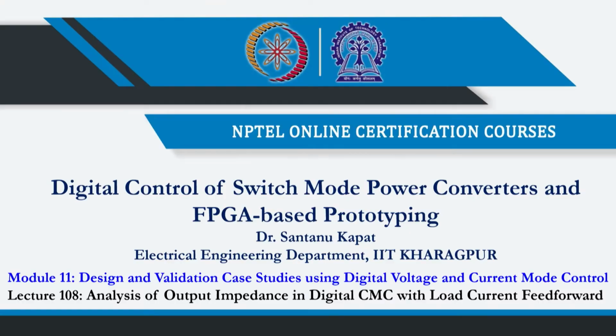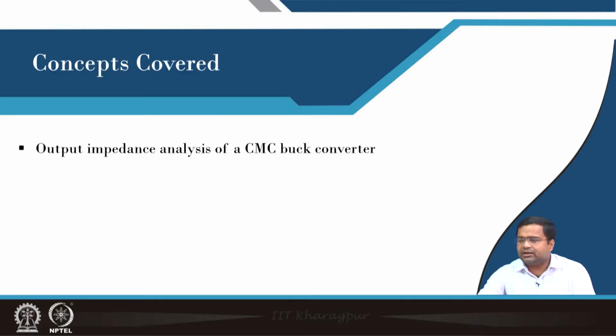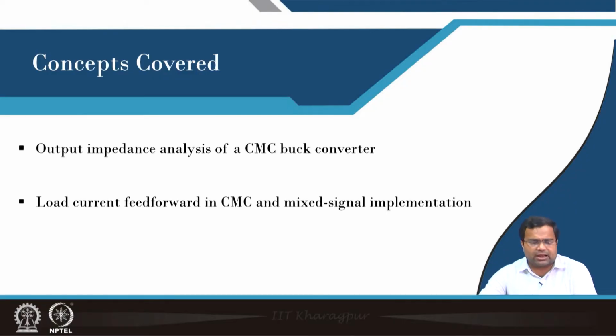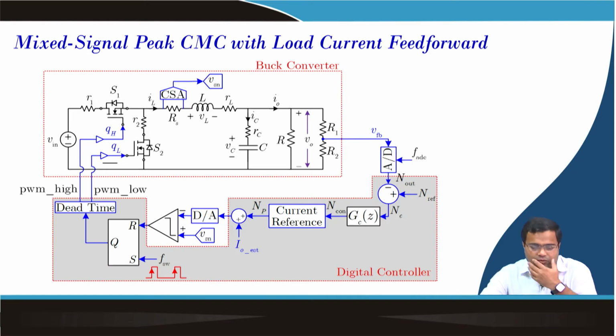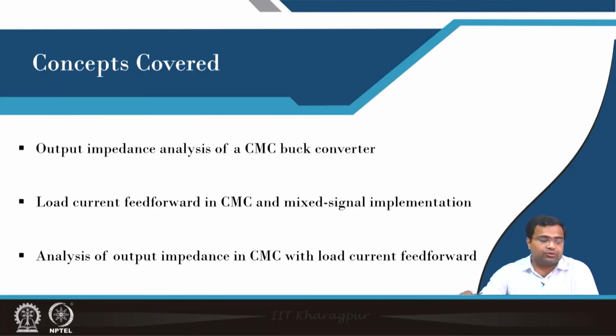Welcome. In this particular lecture, we are going to analyze the output impedance in digital current mode control with and without load current feed forward. So, here we will discuss output impedance analysis under current mode control, and then what will happen to the output impedance if the load current feed forward is added, and what the output impedance is with and without load current feed forward.